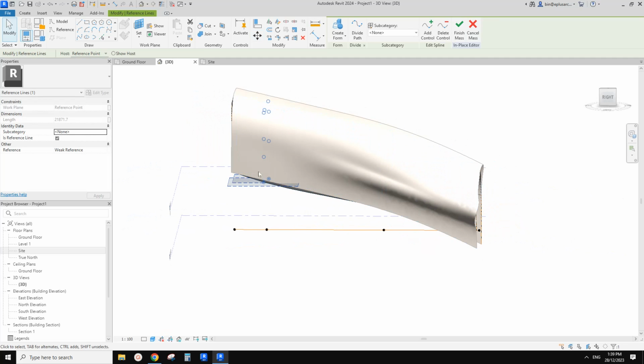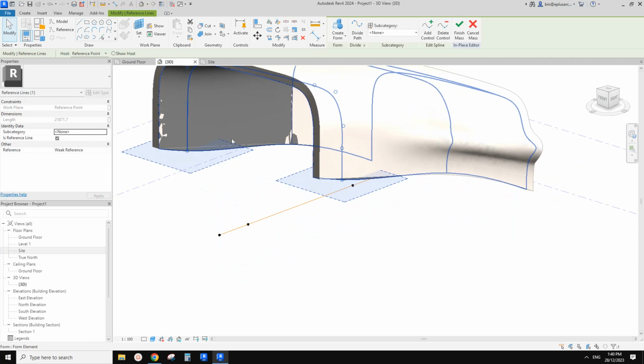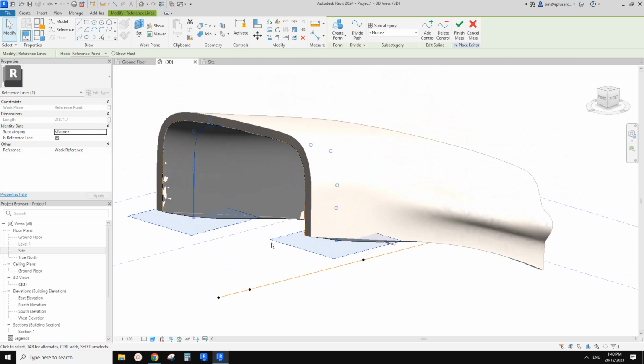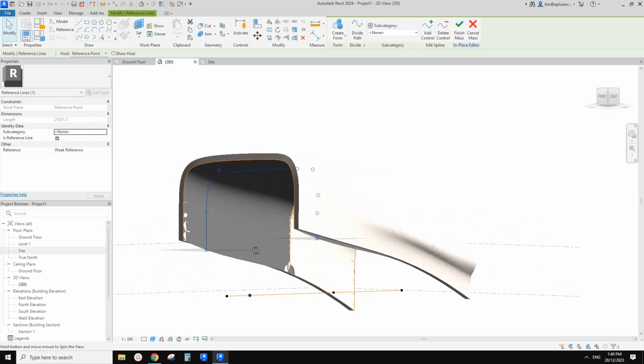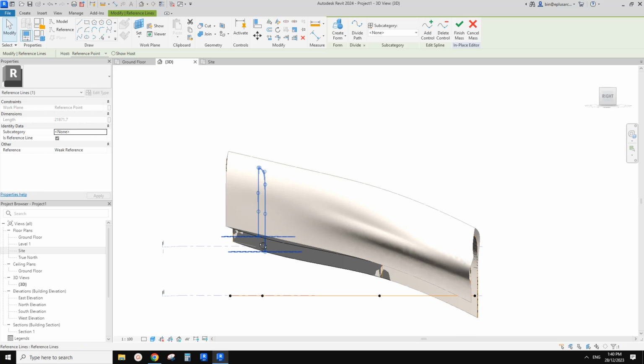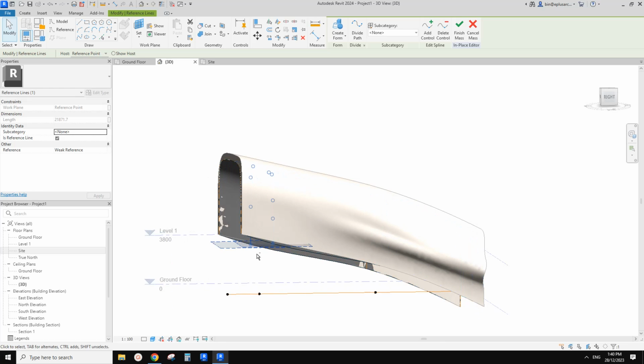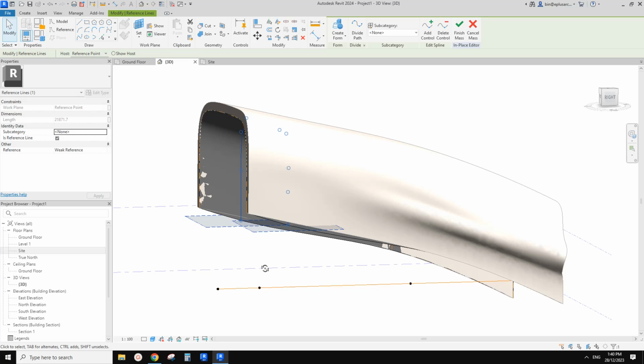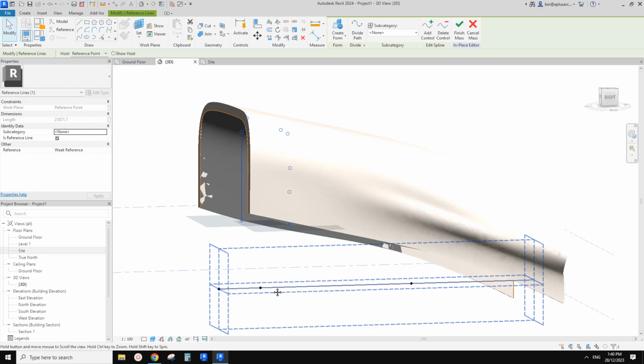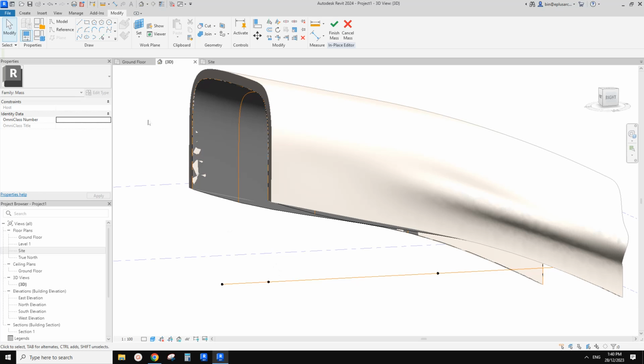But the issue here is that this spline is placed onto this vertical work plane at this point, so we can't rotate it this way. We can't rotate it. So what we need to do is place a point on a work plane, and then, hang on, let me just show you. It's a little bit hard to explain.